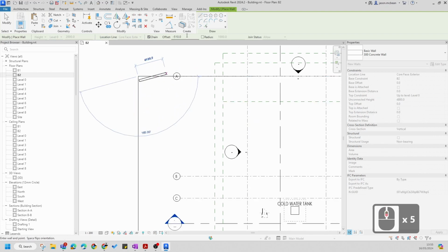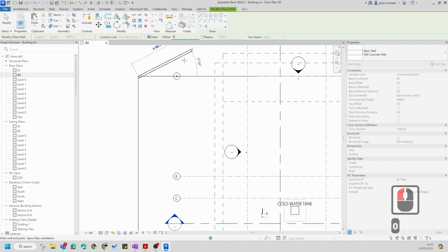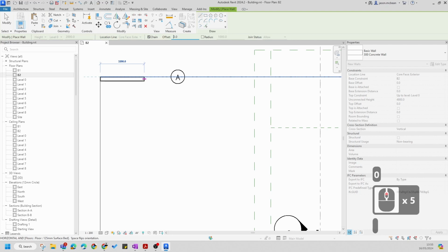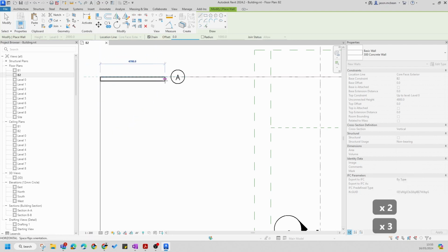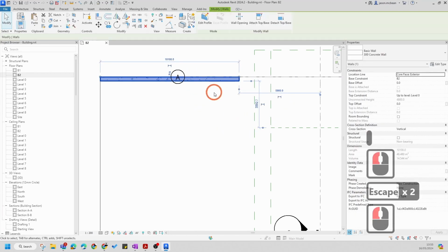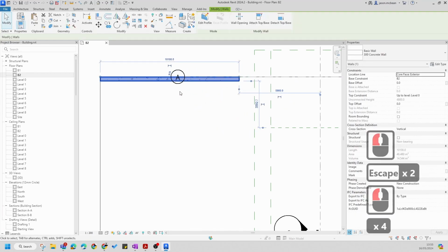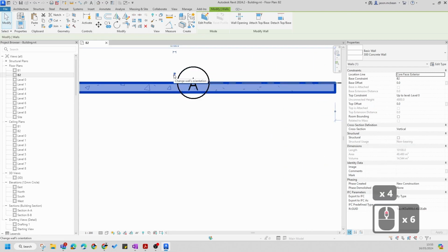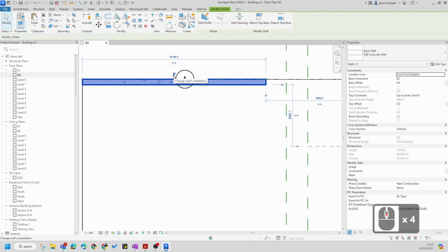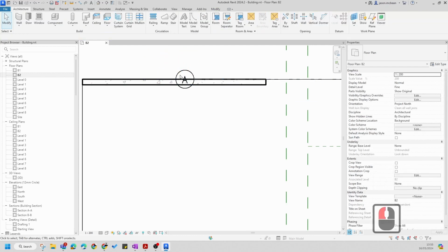Okay, so that offset is that command there, so make it 0. So when you draw the wall and you press space bar, if you're busy drawing, space bar usually flips the wall in a direction. Okay, so if I draw the wall now and I press space bar, you'll see it'll flip the wall. Now wherever these handles, this location, change orientation marker is located, that's indicating that this part is the exterior side of the wall, and that this is the interior side of that wall.